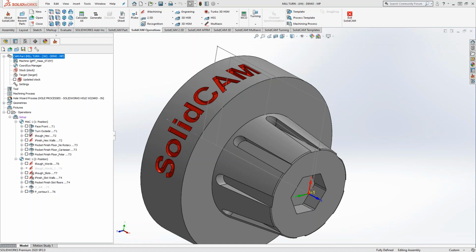And then when you realize what 3D models you actually have, then you can go back and modify it. And if you've made everything correctly, let's say you make your stock out of a series of blocks and you make it as an assembly, if you've mated them all together, then when you change the shape of something, those mates should just realign and set that thing back up as your proper stock. So there's a lot of automation, a lot of intention you can put in your assemblies, in your designs, that when you change one thing, it just automatically updates itself. And then inside SolidCAM, because all of our stock recognition is watching for that, it'll update the toolpath as well.